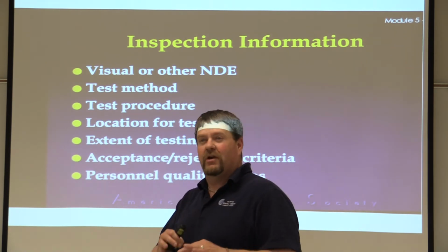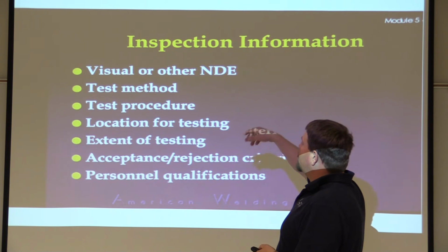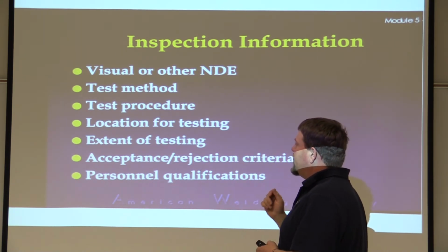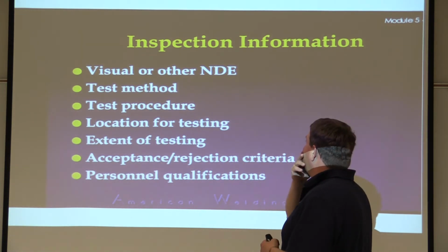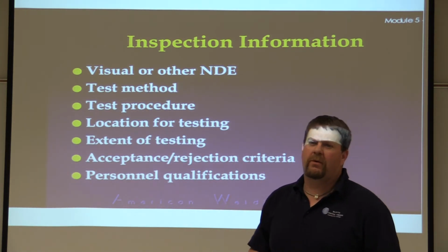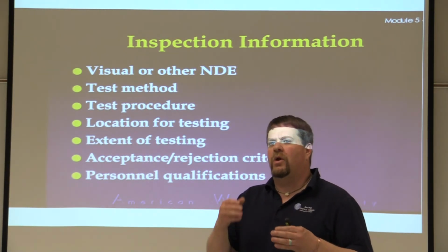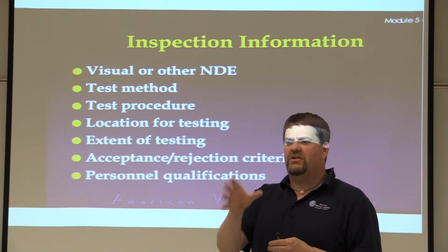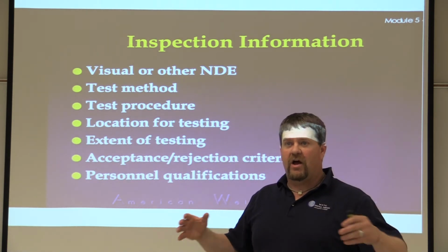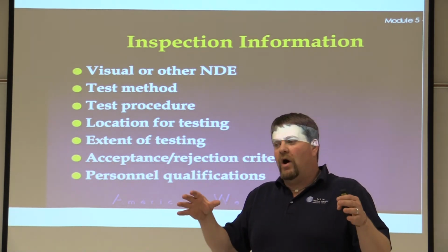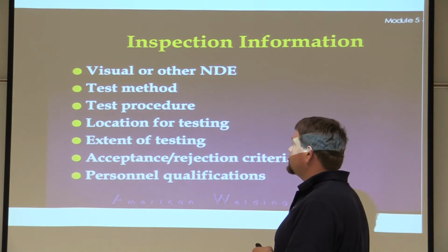I think you're starting to get the point, so I'm going to kind of lay off that a little bit, okay? We're going to move on to this, visual or other NDE, be prepared for it, how to set up for it, and also this tells me how to schedule for it as well, right? So if I need to do a non-destructive examination on the first 20% of the welds, or say the first 20 welds out of 100, okay? I need to know when I'm going to start welding, and then schedule that x-ray crew at that time, which also means I need to schedule the entire job to shut down while they come in and use radiation to x-ray that, all right?